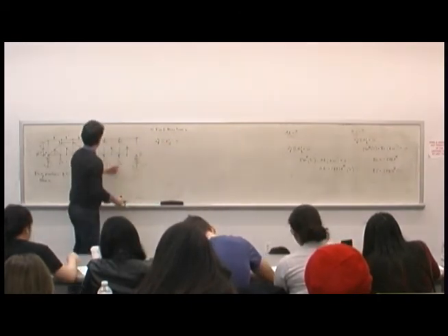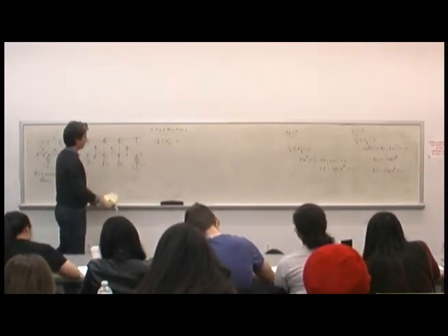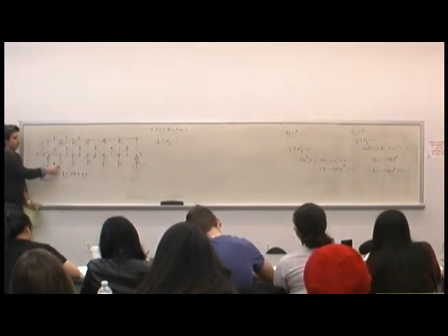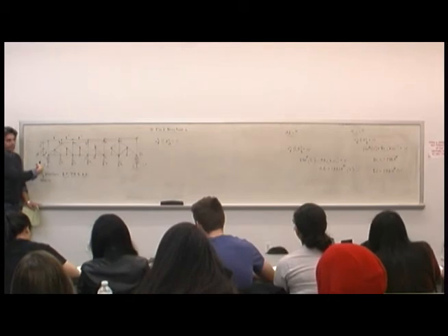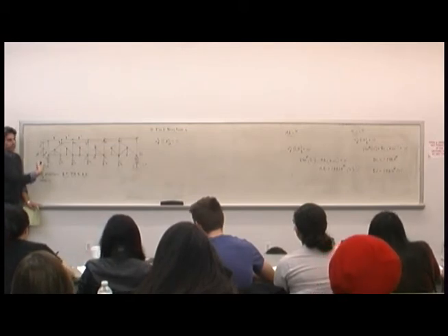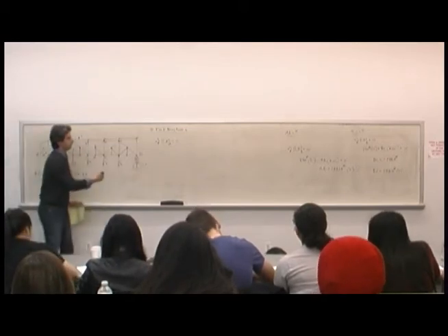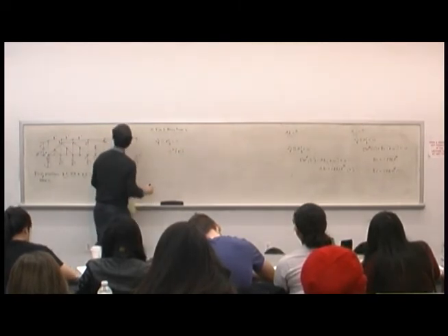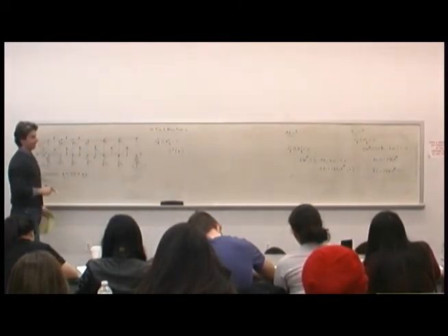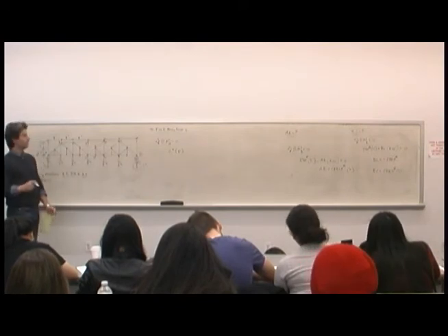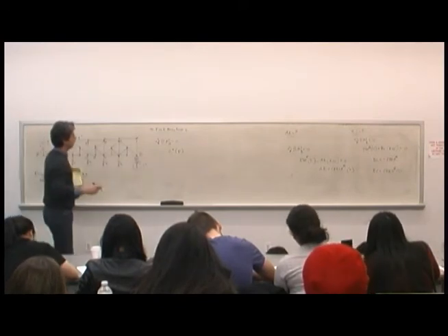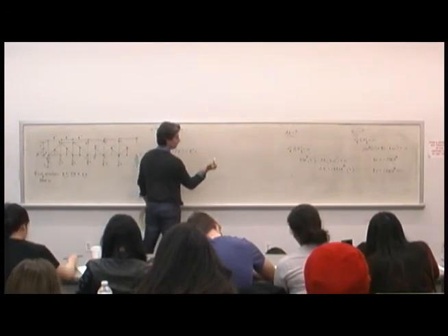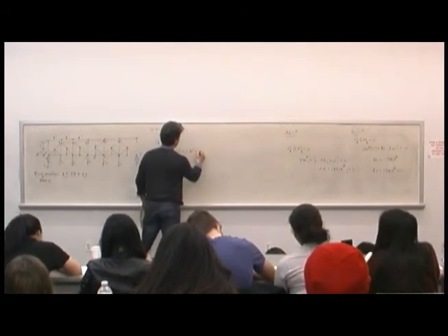You just have a bunch of forces you've got to deal with. So how do I do it? What do I do with the 2 kip force? Spinning around A in this direction, it's 2 kips times 4 feet. Plus 8 kips times 8 feet.